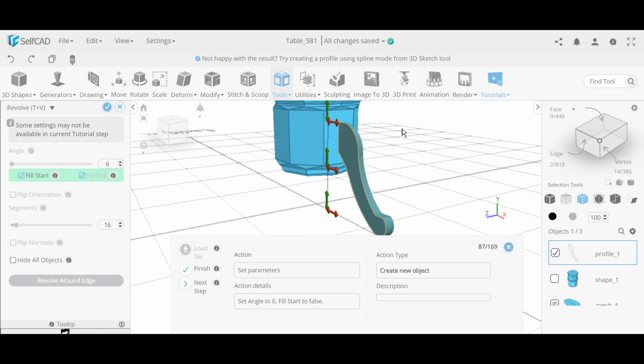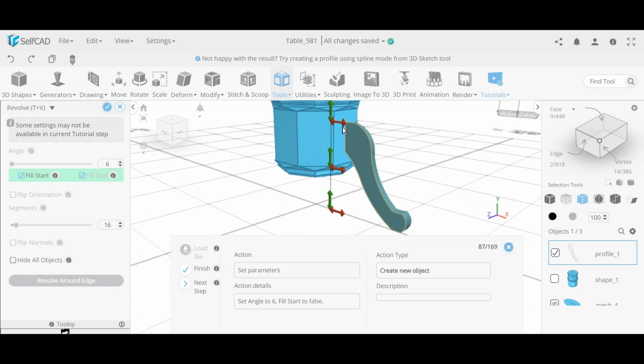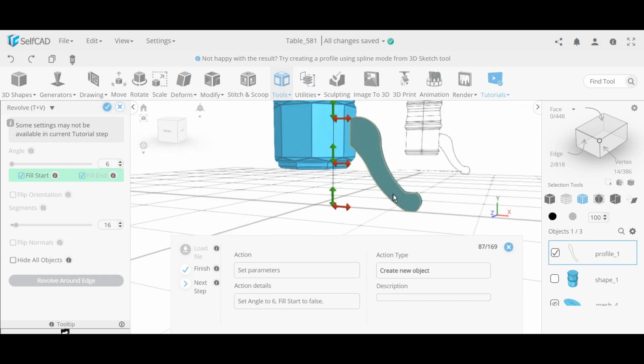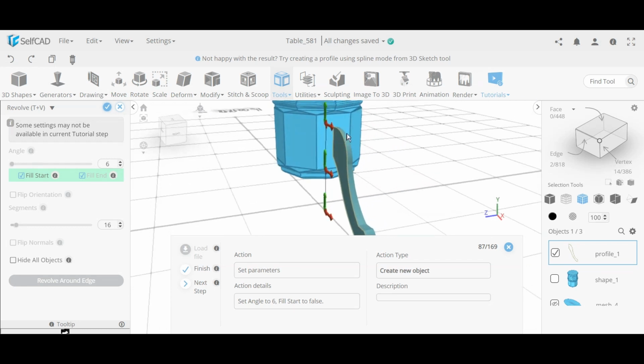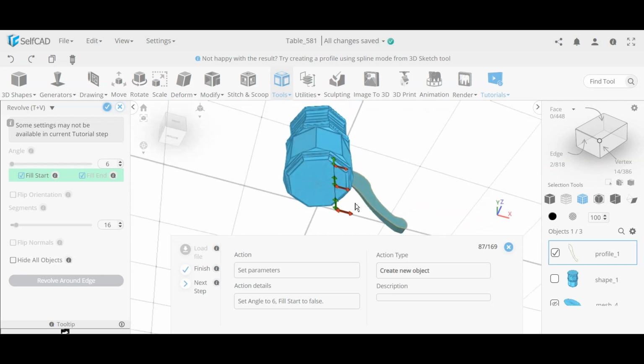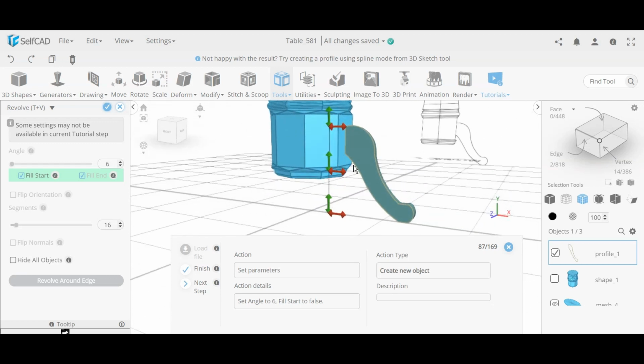But if we use this revolve effect, what's happening is the axis here makes it thicker over here, and the closer you go to the axis that we use, it becomes thinner and thinner. If you had tested this before the tutorial, if you would move this gizmo over here to an angle that goes to this axis, an angle to the length of the leg, then the thicker part would be this section, symmetrically thick, and thin would be over here, the bottom part, because the axis would be this side.